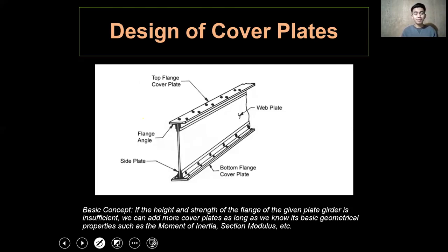Before we proceed with the design part, the basic concept of designing a cover plate is that if the height and the strength of the flange of a given plate girder is insufficient, we can add more cover plates as long as we know its basic geometrical properties, such as its moment of inertia, section modulus, and more. All right? So how are you going to determine the section modulus or the moment of inertia of a given cover plate or of a given